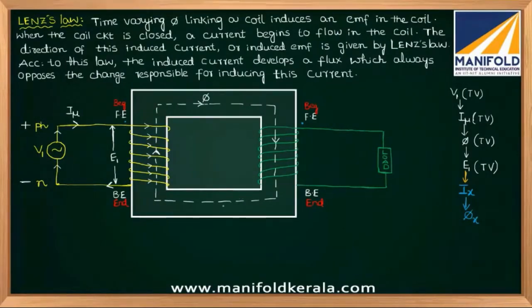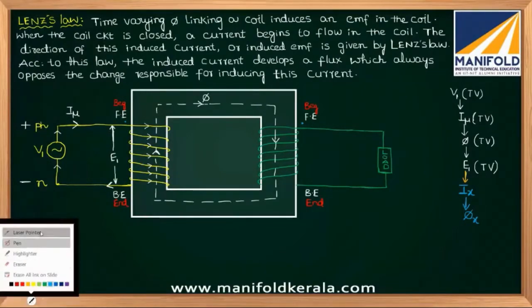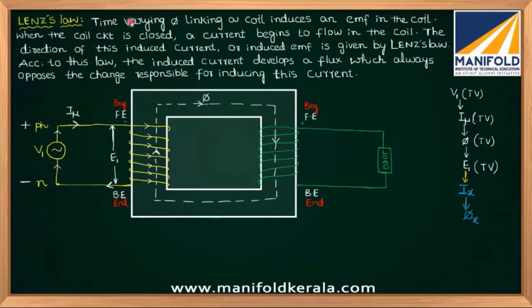Okay. Now please try to see the statement which I wrote on the screen. Lenz law means what? You tell me, guys, first of all, why are we using Lenz law? In a transformer, I told you what is the type of EMF induced? Static EMF, no? Yes. If you want to know the direction of static EMF, or I can say, the polarities of static EMF, then we have to use Lenz law.